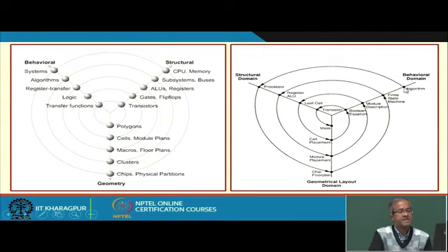This algorithm specification you first synthesize or decompose into a structural design which consists of some interconnection of, as I said, some processors, CPUs, memories, IOs, etc. Now, this netlist you translate into physical domain where you do some kind of a chip level floor plan, like you decide that on your chip you can place your processor here, first memory here, second memory here, the IO chips here. So, you do a tentative floor plan on the silicon, how you will be placing the different very high level modules.